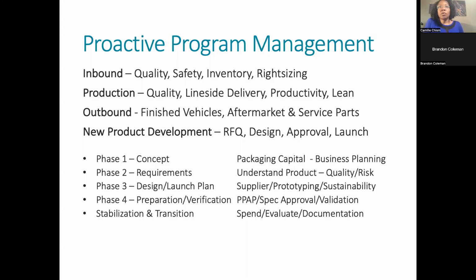Design, again, is looking at all the aspects from the beginning, when this part first gets built. What are the properties of this part? Where is it delicate? Is it an electronic part or is it plastic? Is it class A? Just understanding the design elements of the part so that you can design a pack that meets the needs to protect it, as well as display it line side, knowing how much space you have. And then, does this need to be shipped out anywhere, if it's an aftermarket or after service part, for example?